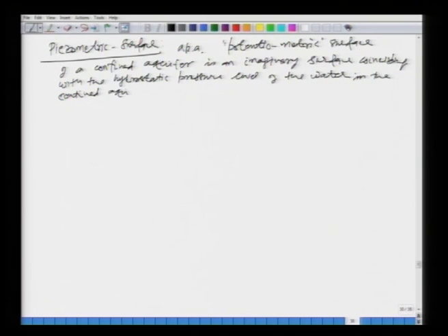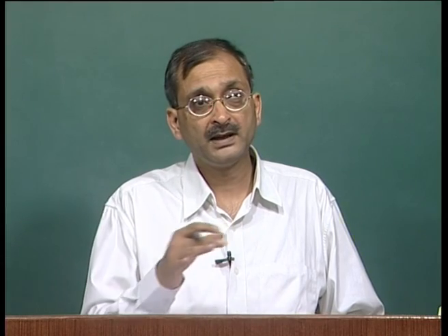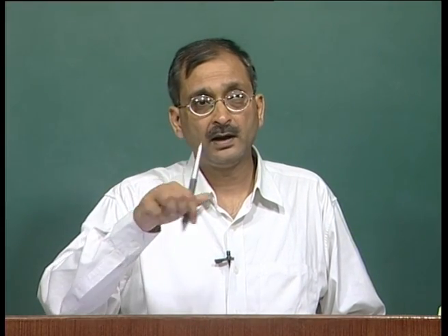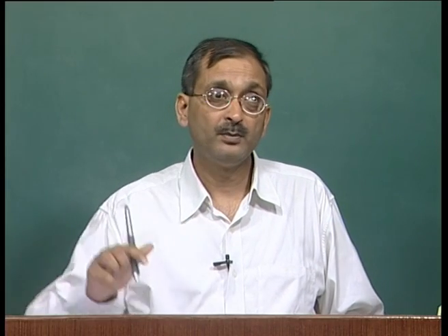So, it is an imaginary surface which coincides with the hydrostatic pressure. As we said, in a confined aquifer, the water is at a higher pressure. So, the hydrostatic pressure may be higher than the atmospheric pressure. Whatever it is, if you dig an observation well, the water will rise quite high, and if you join that surface, that is called your piezometric surface.